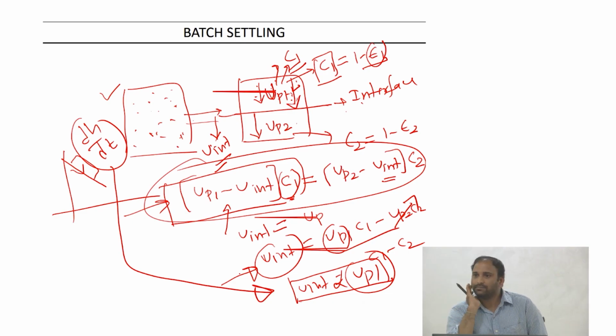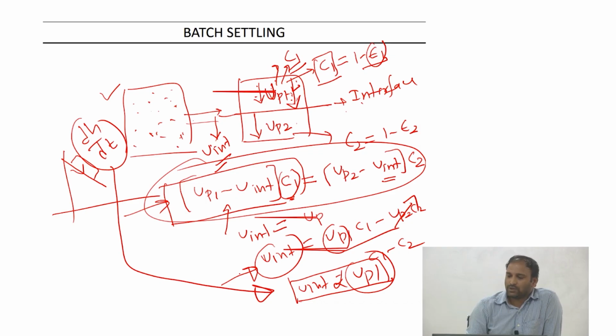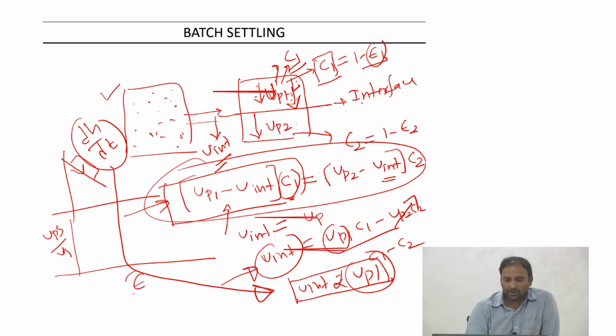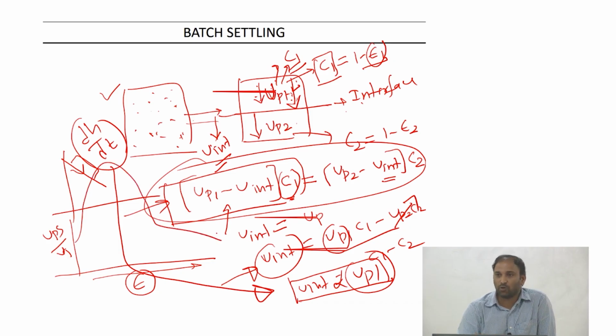Yes, this is only when C2 is 0. But when we did u_p over u_t as a function of epsilon, epsilon would be changing depending upon the sedimentation that is occurring, all the time. Therefore, what people do is use the flux plot. I can take 2 points, get a tangent, and from the slope there are ways of calculating u_interface and relating that to interface velocities.